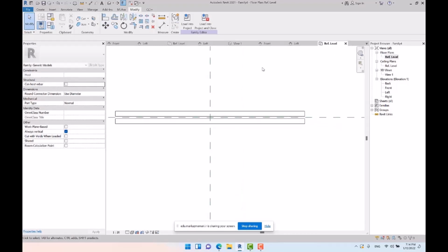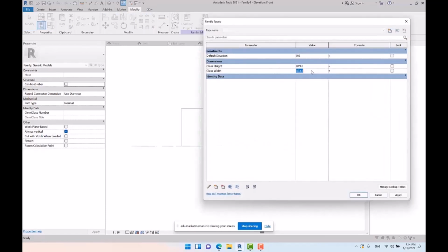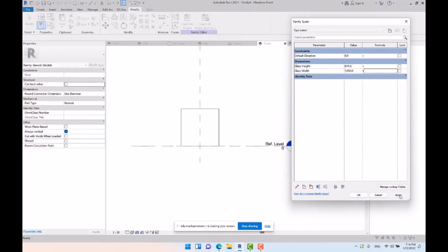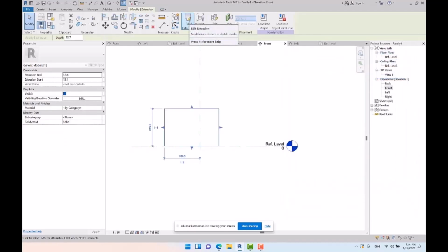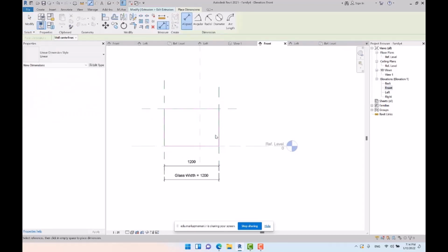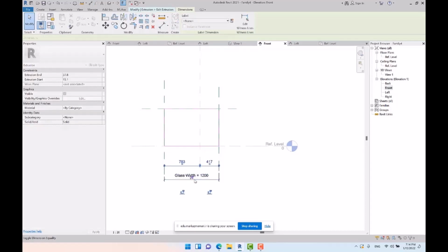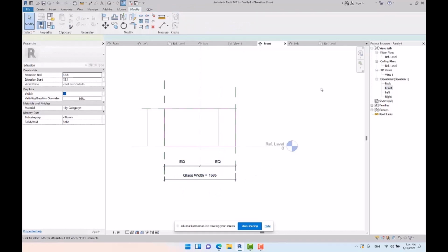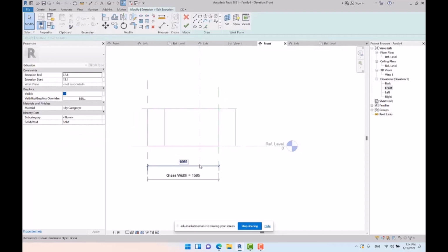Okay. Well done. Right now I want to test it. As you know, I've always been emphasizing testing the parameters, so just be patient and check all of the parameters. 1200, apply and OK. Check this out. As you can see, it is working correctly. There is a problem, which is because of the constraints. I open the edit boundary command, and the position of the extrusion is not fixed in relation to the reference planes, since when we make copies, some of the dimensions which are equal would change. Finish. And it does work out only at a specific position.